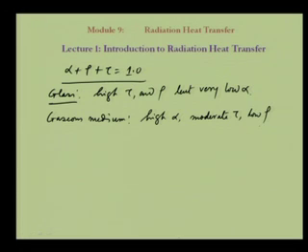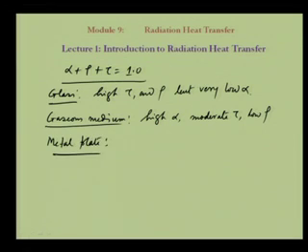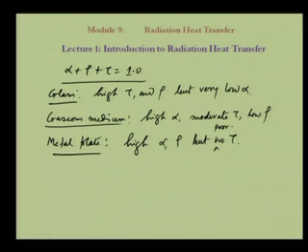So, this is what it is for a gaseous medium. Similarly, if we say metal plate, okay, so this is the case. In case of a metal plate, absorptivity and reflectivity are high, it can have high absorptivity alpha, high reflectivity also, but no transmittivity or poor. So, that is what is happening.